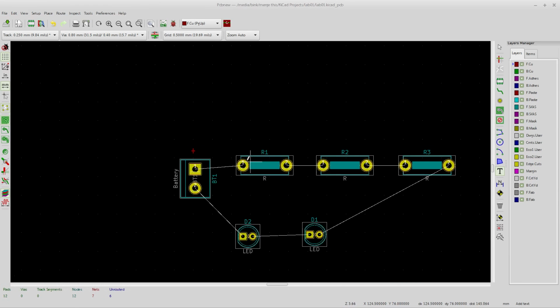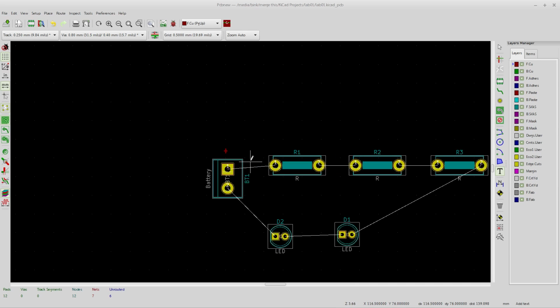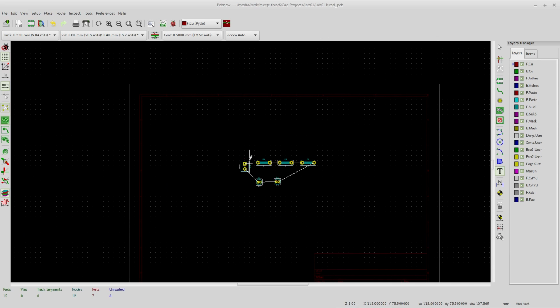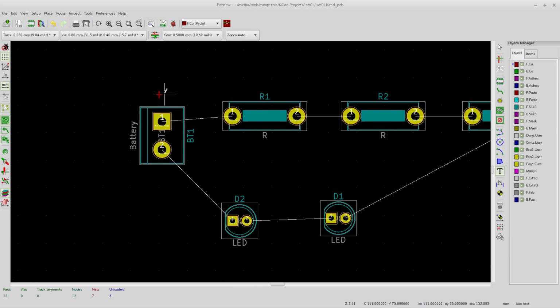Make sure that your board house can actually print these small symbols, the small fonts. By the way, notice what I just did here, another tangent. I added in a symbol, and it's in red. It's in red because it's actually a copper pad right now, because I accidentally did this on the front copper. More on this down the road as it goes on.